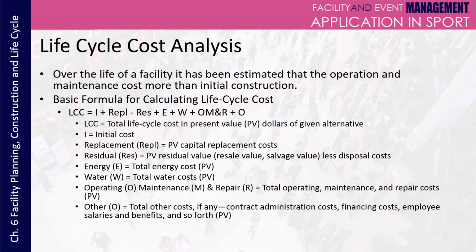While the initial construction cost of a sports facility is significant, it's only a fraction of the total expense over its lifetime. Studies estimate that operation and maintenance costs far exceed the initial investment. This is where life cycle cost analysis, or LCCA, becomes essential. If we break down those life cycle costs into a formula, it looks like this. LCC is the total life cycle cost in present value dollars of a given alternative. I is for the initial cost.